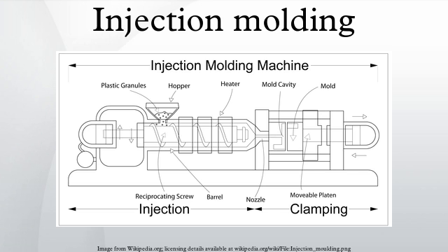Equipment. Injection molding machines consist of a material hopper, an injection ram or screw-type plunger, and a heating unit. Also known as presses, they hold the molds in which the components are shaped. Presses are rated by tonnage, which expresses the amount of clamping force that the machine can exert. This force keeps the mold closed during the injection process. Tonnage can vary from less than 5 tons to over 9,000 tons, with the higher figures used in comparatively few manufacturing operations.